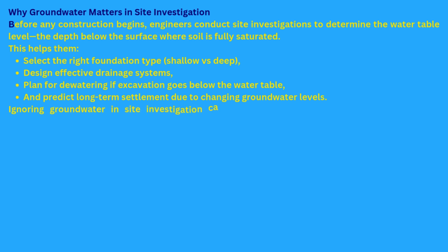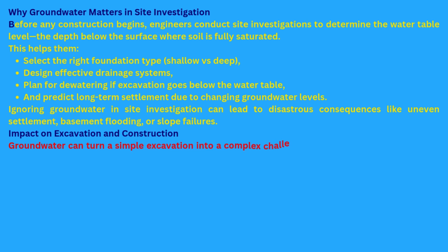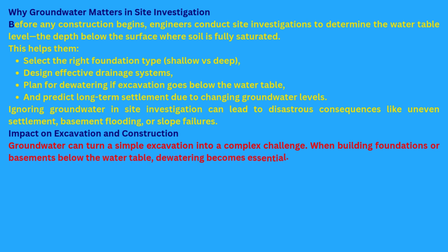Ignoring groundwater in site investigation can lead to disastrous consequences like uneven settlement, basement flooding, or slope failures. Impact on excavation and construction. Groundwater can turn a simple excavation into a complex challenge. When building foundations or basements below the water table, dewatering becomes essential.